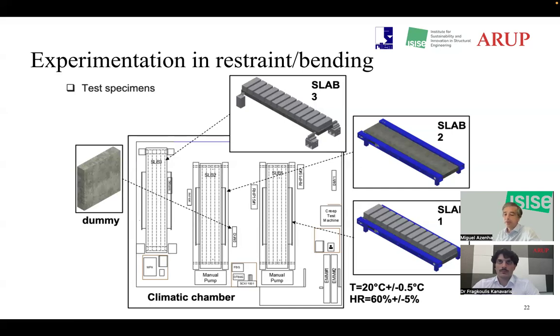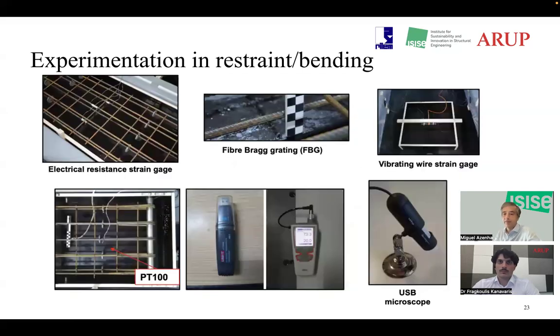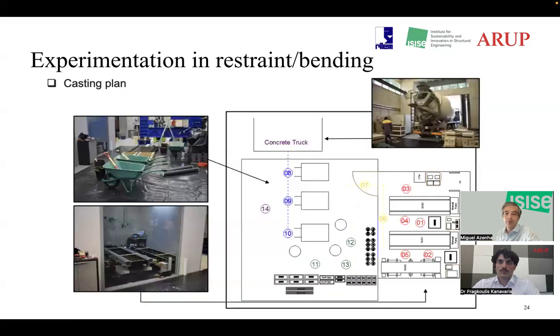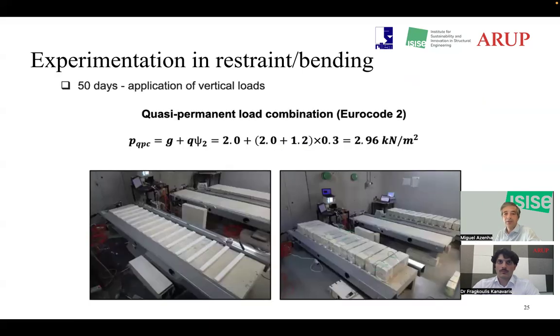So we measured the behavior of all this with several devices, and I will not go into details. These are just illustrating pictures. Also, it created the need for a very intricate set of casting and care for curing and for the early ages, because all of this was really important to make sure that the experiment was traceable. And ultimately, at the age of 50 days, we applied a quasi-permanent load combination with the load that you see on screen, and we made sure that the load was applied uniformly and progressively, and we monitored all the process.